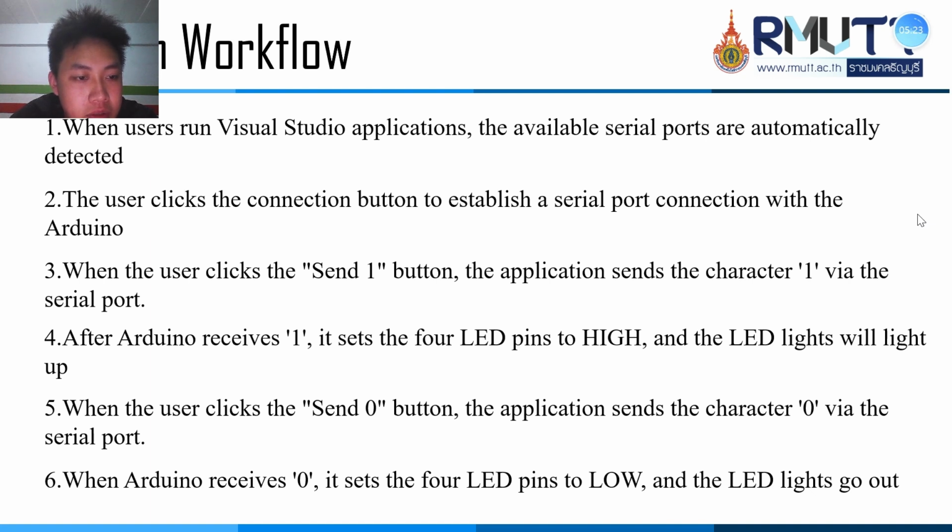The third one: when the user clicks the Send 1 button, the application sends the character 1 via the serial port. The fourth: after the Arduino receives 1, it sets the 4 LED pins to high.